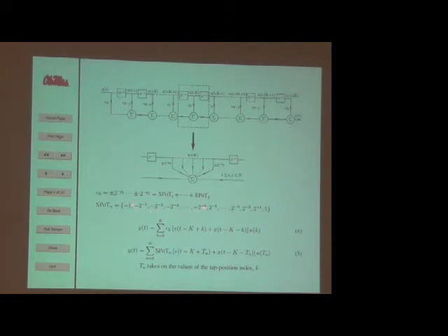I'll limit the range of these things so that the smallest magnitude of my signed power of 2 is 2 to the minus B, and B is just something I choose to avoid having to shift my word more than B bits. It's also important to control this number because you don't want your word size larger than it needs to be. It makes the filter more complex than it has to be.